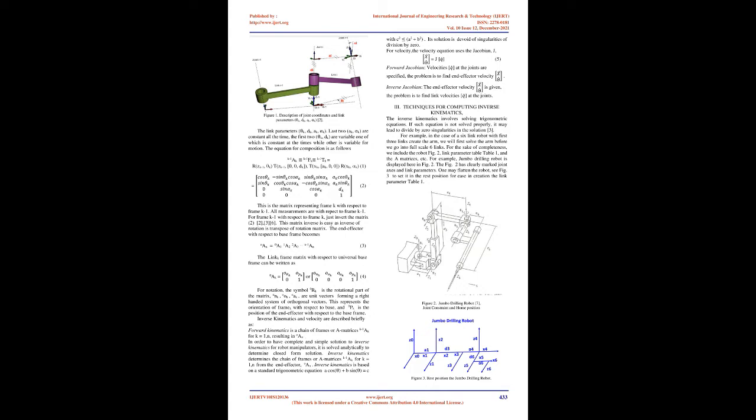In practice, a robot has 6 DOF; an articulated robot may have all revolute links. For a robot with 6 DOF, normally the arm has 3 links and the wrist has 3 links. Some robots may have 2 to any number of links. In any case, in general, the number of links may not be equal to 6.